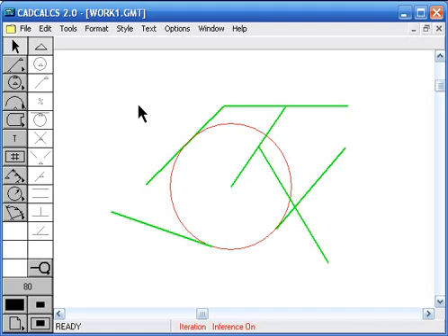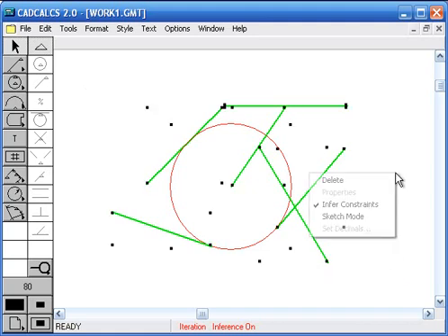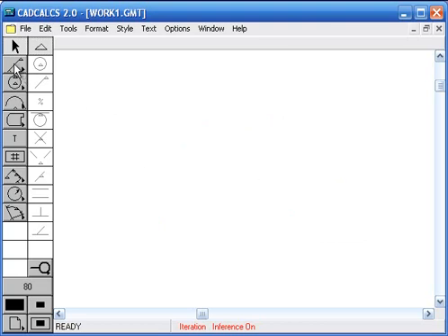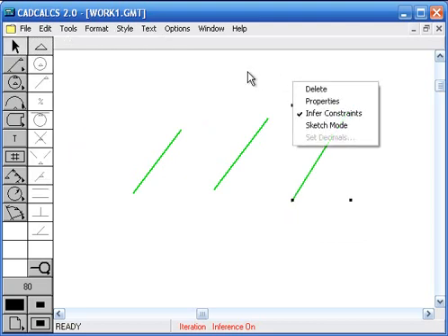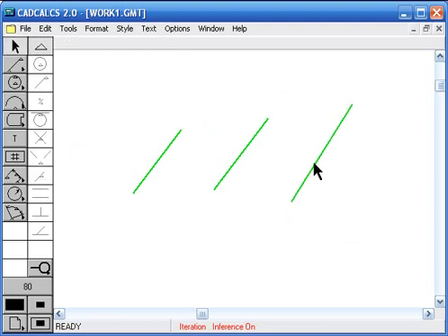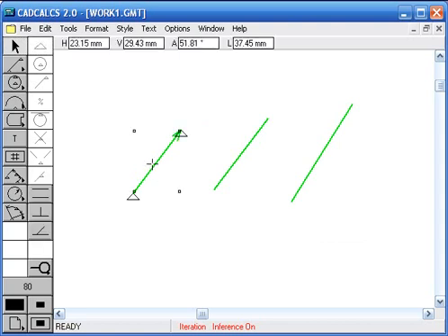Next we will go into what we call numerical constraint. Let's say I draw 3 lines, and I want the length of this line to be equal to the sum of these 2 lines. Anytime you click on a geometry, if the value bar is displayed, this shows the current values which are controlling the geometry.